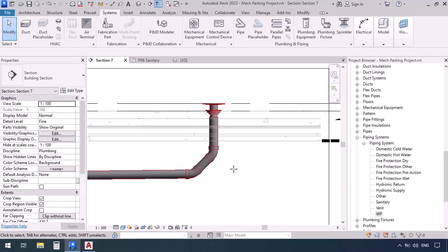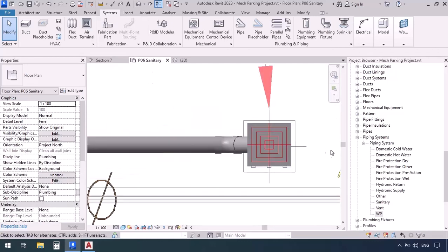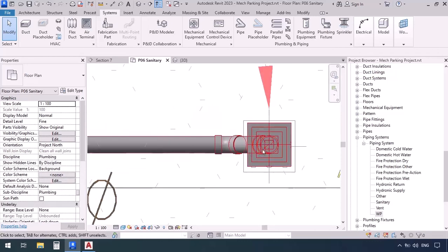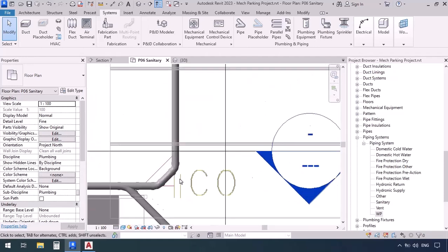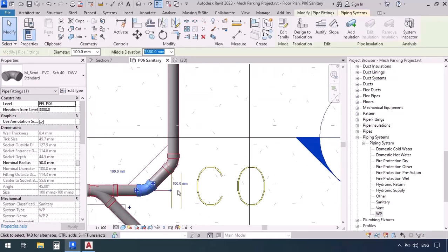Alright, so if your drain is too off course, you wouldn't be able to draw anything. You would get errors or no auto-route solution, or the wrong side error which we just saw. Or if your distance is very little, you would get an extra reducer and end up with a tilted drawing. So always remember to have your axis all aligned. So remember, even if you feel like you've placed your drain a little bit off course, make sure to align the axis.